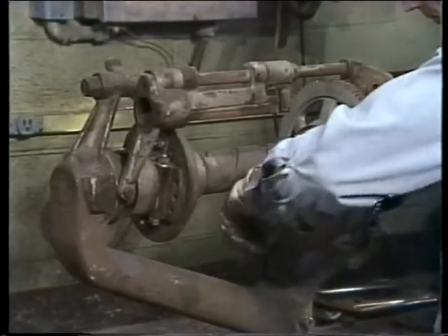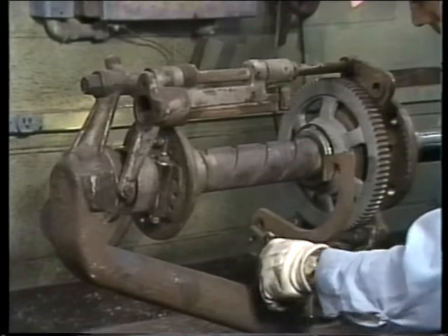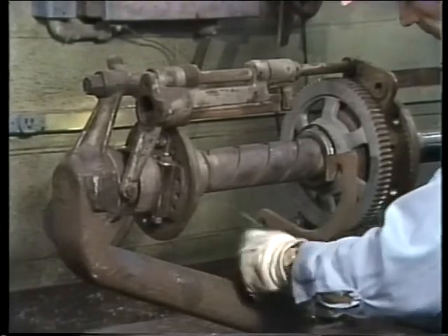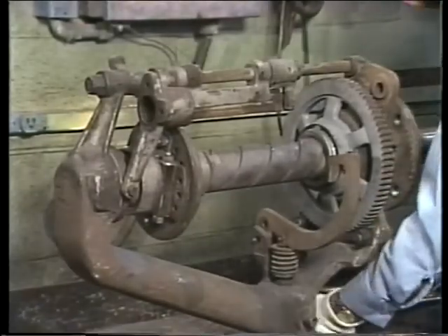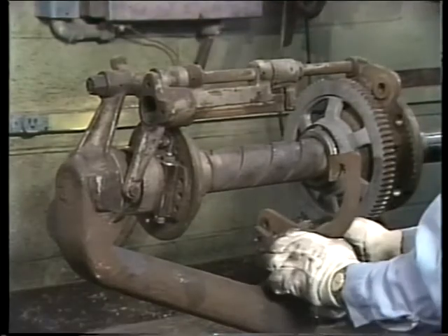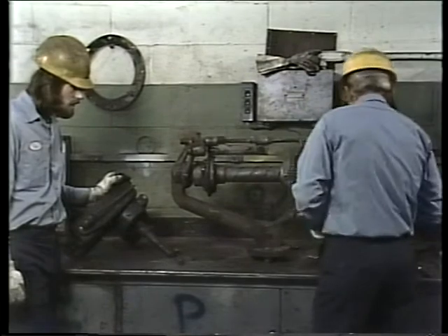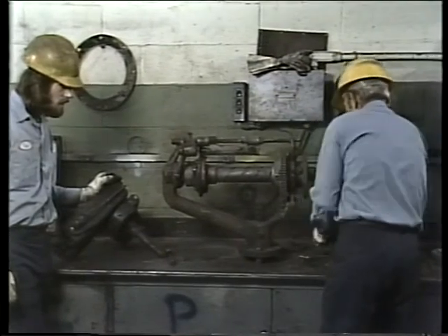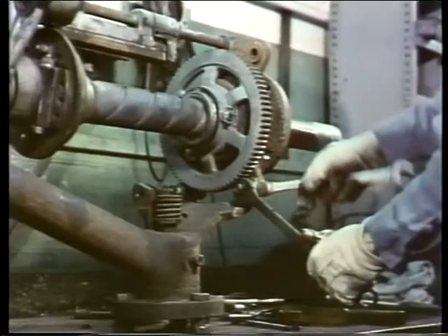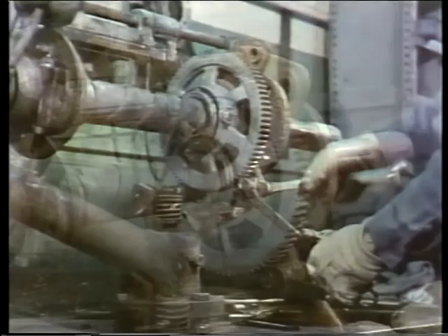In order to remove the element, the valve trigger has to be out of the way, so it's next to be removed. Cotter keys hold the pins on the pivot and the valve stem of this particular soot blower. Once the valve trigger is removed, taking off the front mount and drive gear will allow the element to be pulled. In our example, the front mount is held on by 3 nuts and bolts.